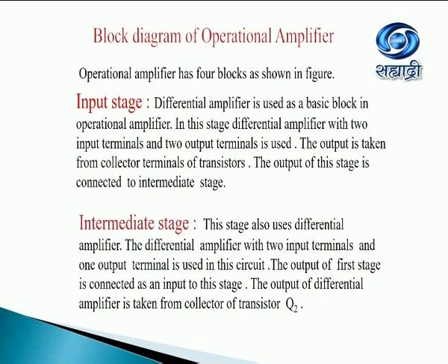Input stage. Differential amplifier is used as a basic block in operational amplifier. In this stage, differential amplifier with 2 input terminals and 2 output terminals is used. The output is taken from collector terminals of transistors. The output of this stage is connected to intermediate stage.